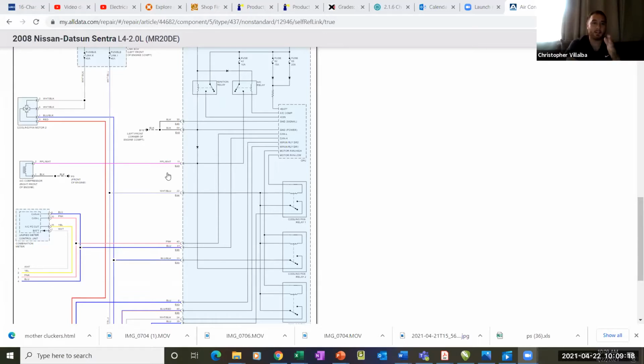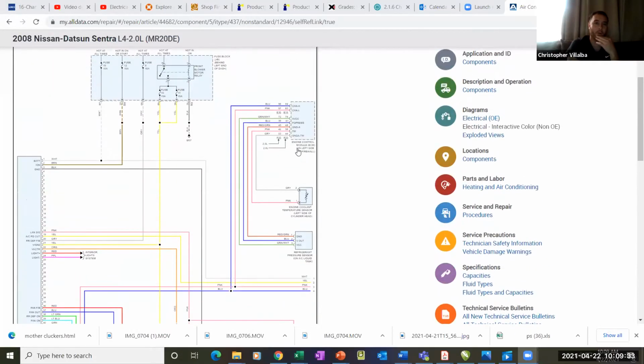Yeah. I'm just trying to wonder why, when we turn the blower motor, the fan, on high, and then push the AC max button on with the engine running, the clutch just wouldn't engage. So we were trying to figure out what it could possibly be. Right. And it could be you got a bad pressure switch, or you don't have enough pressure in there.